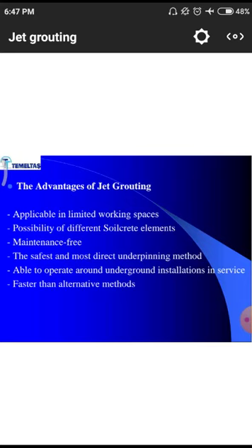around underground installations. Normally, whenever we have a structural repair, for suppose a structure where the total structure is sinking on one side, it may require some jet grouting below the foundation. Those kinds of works are also operated using these techniques.